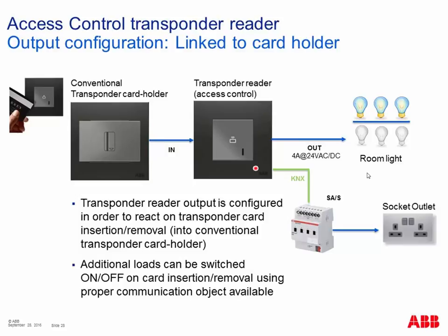What about, again, the controlling of the electric lock? The electric lock can be controlled also in this case with a KNX communication object. In addition, remember that when you insert or remove the card, you have an additional communication object for notifying that the card is inserted or removed. We'll show you this later in the presentation.